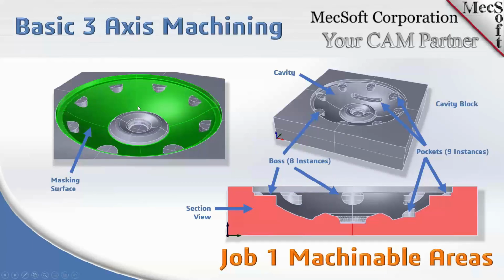The reason we call that a masking surface is because we want to basically mask some of the features underneath the surface, or protect the features from being machined. So we're going to be going through stages of machining, and that's the main reason we're calling that the masking surface.